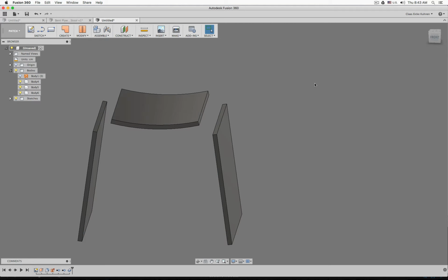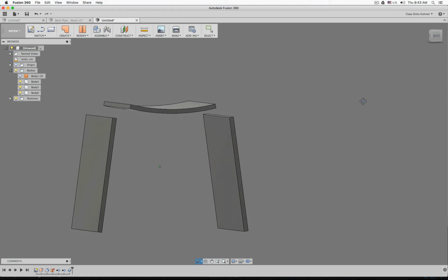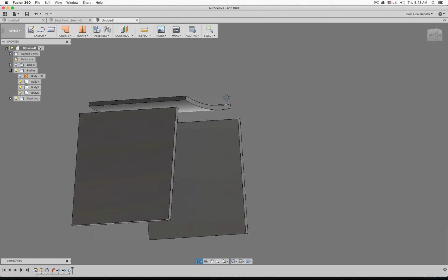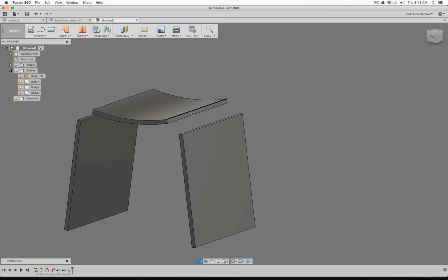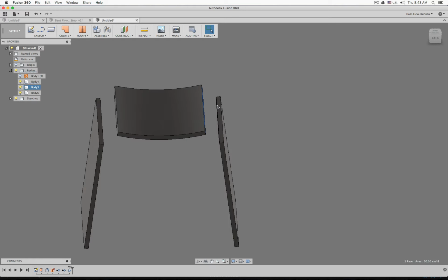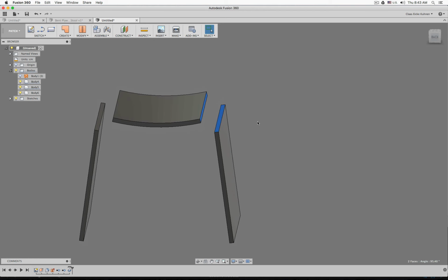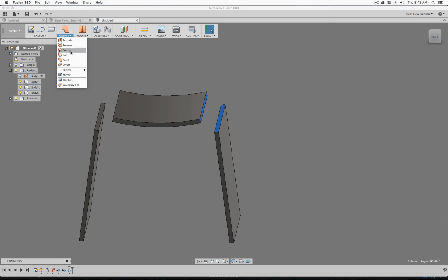Now we have our surfaces. So now it's a volume, and now I can say from this face to this face, create me a transition. In Blender, the command would be called bridge, or in T-Spline, it's also the command bridge in Fusion. And in other CAD programs, sometimes they call it blend.